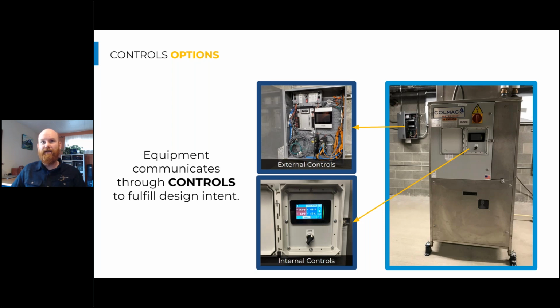And like with some of these earlier implementations of this technology, understanding what's happening and why it might have happened is really important whenever we have a problem. The internal controls of the heat pumps, depending on what manufacturer you're specifying, might have some of that capability, but to really ensure a robust understanding of the system operation and how well it's performing, as well as any notifications on maintenance or alarms or other aspects, the external controllers really are worthwhile in some situations.